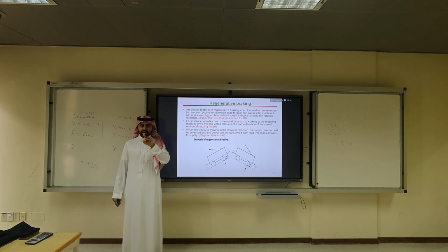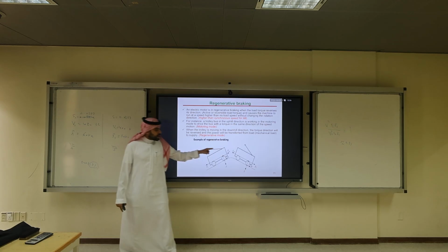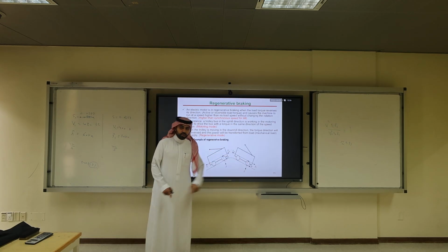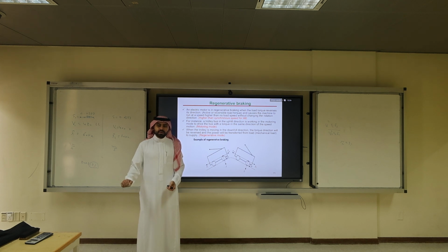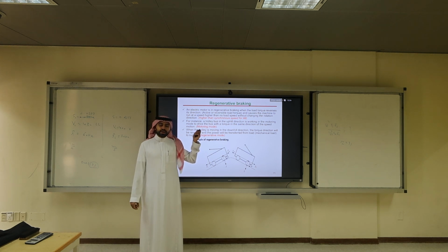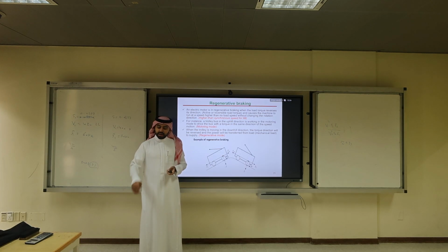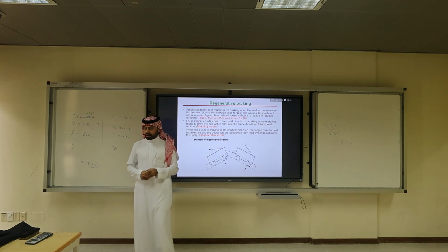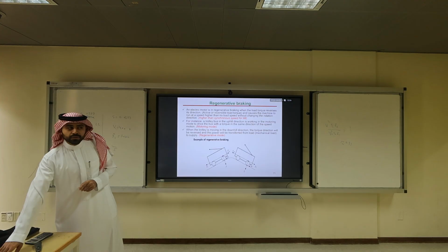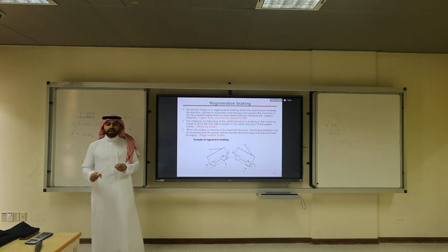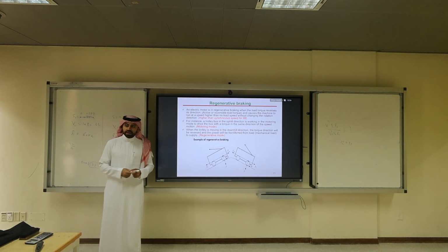In the hybrid vehicle, go downhill. Put it in N. Will you see regenerative braking? I don't expect so. Take the regular gasoline car and put it in N and the car goes downhill. Would you consume gasoline? No. So in either case you will not consume gasoline. But if you drive an EV and put it in N, you will not have regenerative braking.